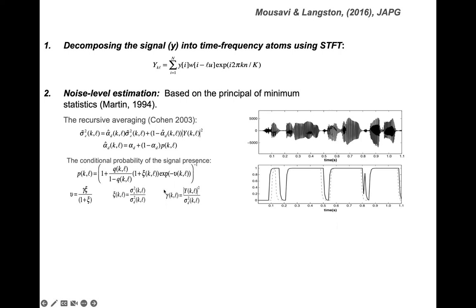Then in the second iteration, the smoothing excludes the relatively stronger signal components, and past spectral power values of noisy measurements during the periods of signal's absence are recursively averaged. Using this, we will have an estimation of noise level from the whole duration of the seismogram, without requiring any arrival time information.